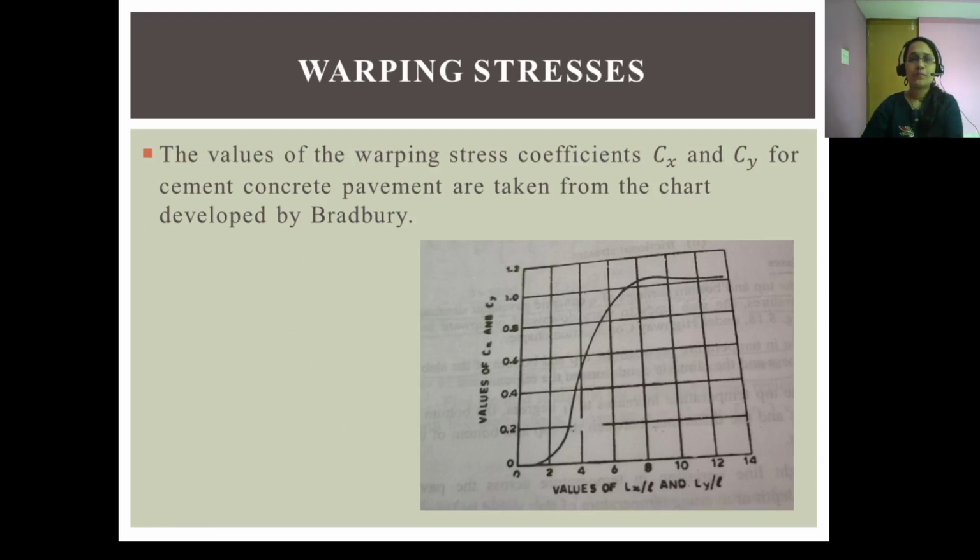The values of the warping stress coefficients Cx and Cy for the cement concrete pavement are taken from the chart. We will get the values of Cx and Cy based on Lx upon L and Ly upon L values.